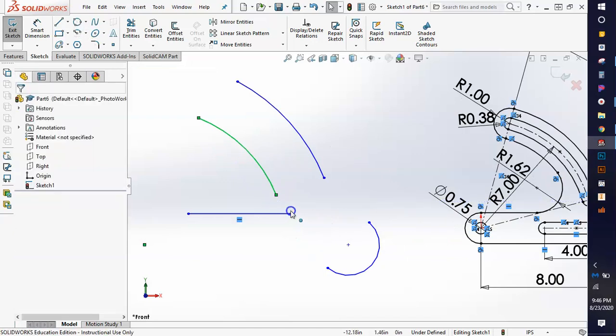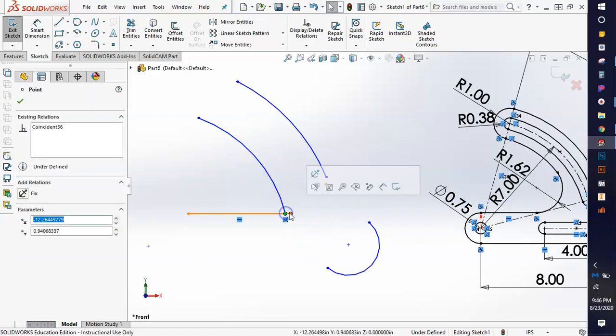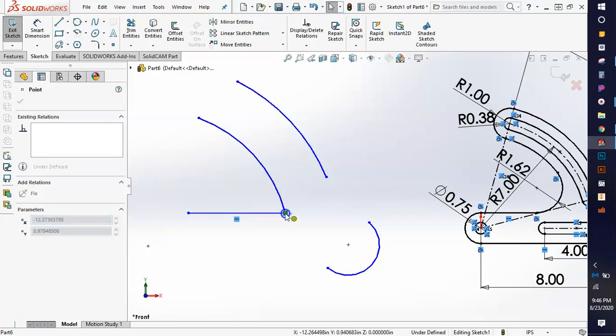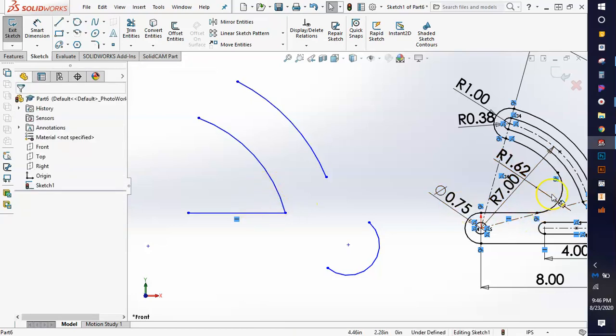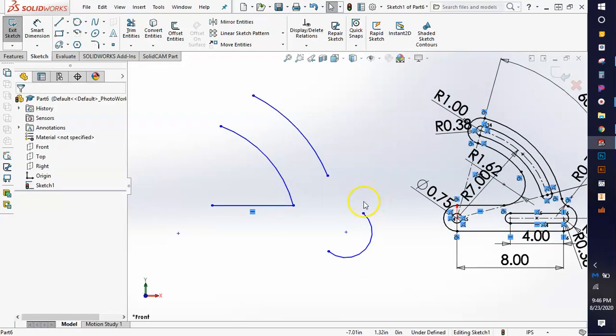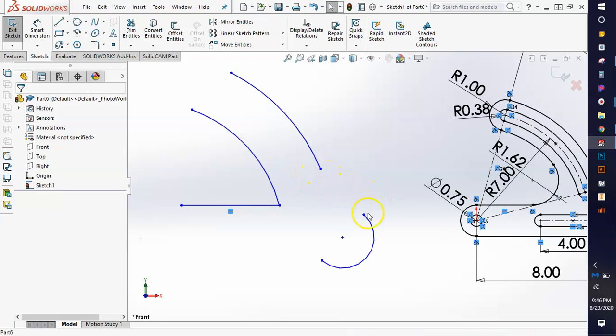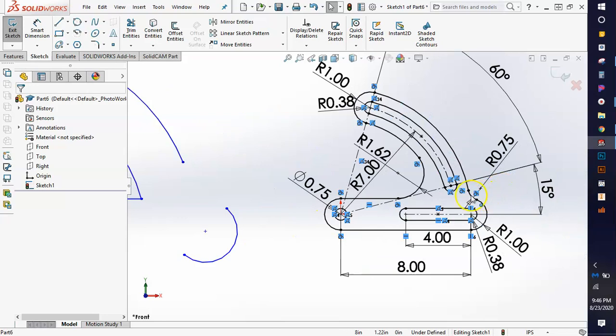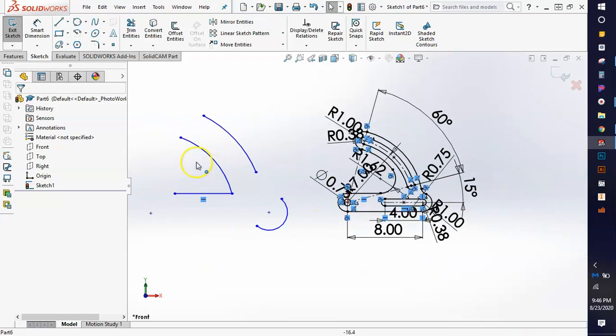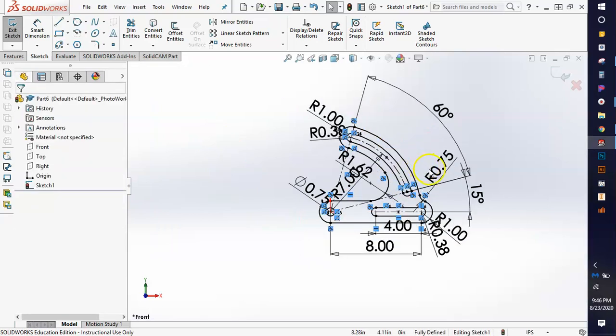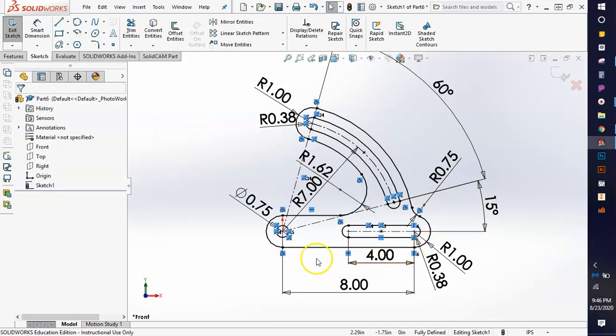Now, where these two crossed, then you could have actually filleted those. So this crossing here would be this fillet, and down in here, you would just need kind of a fillet where those two cross, and that would be this portion. So you wouldn't have had to trim a whole bunch of stuff and fix up a whole bunch of stuff. There's different ways of doing everything, but for right now, this thing is fully defined. We got to that point, so that's good.